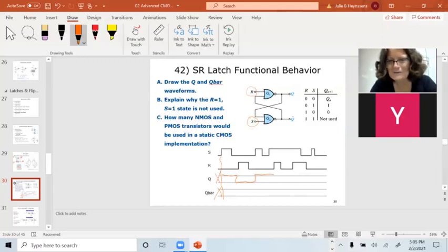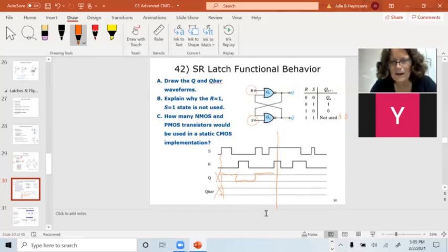And we determine for this particular latch, I get 0, 0. So I've done something really bad in this time frame. I've set and reset true at the same time. What happens is Q goes low. Normally Q bar would equal the not of Q. But as soon as I did that bad thing, they're both low. And they're going to stay both low until reset goes back false. It will go back into a known state. It'll behave once I stop doing that.